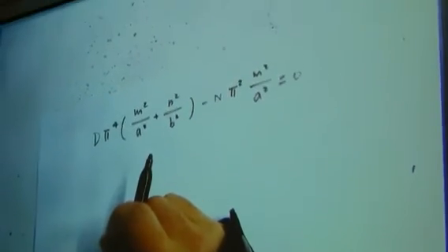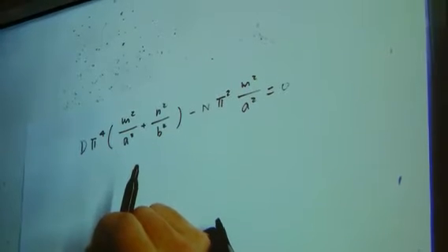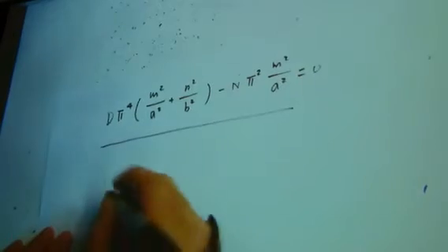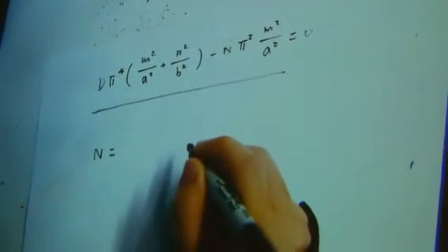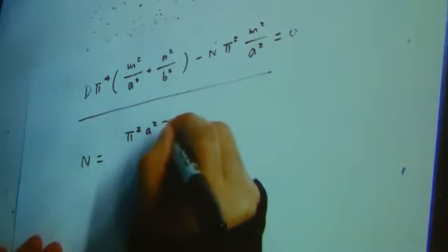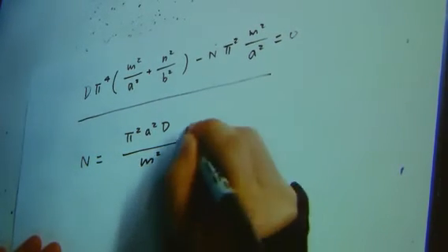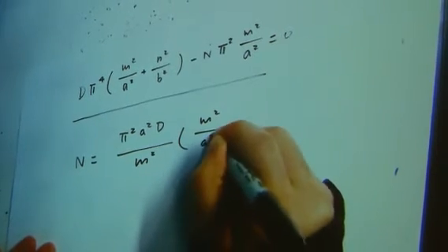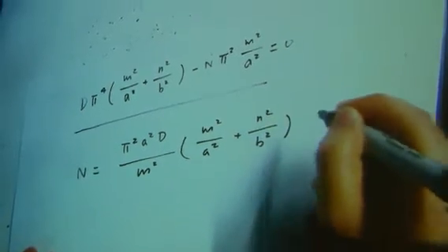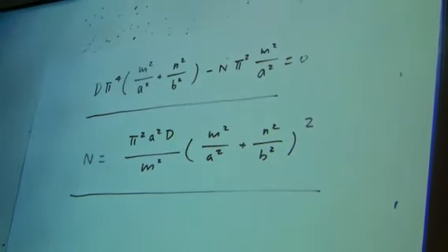In column buckling, we are solving for P. In plate buckling, we are solving for N. Right? N is the applied loading along x direction. This is the equation, one equation, one unknown. The unknown is N, so you can solve for N. This is a critical loading for a plate to have buckling.